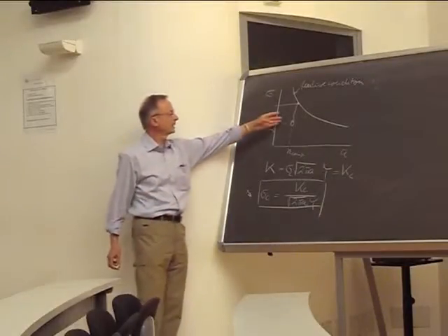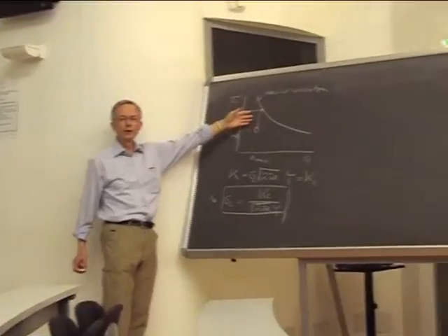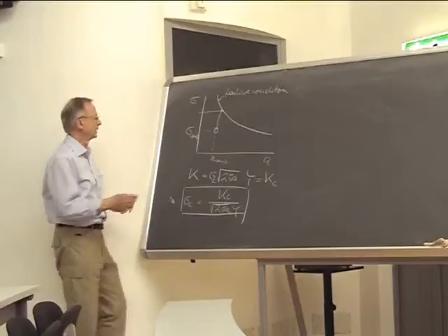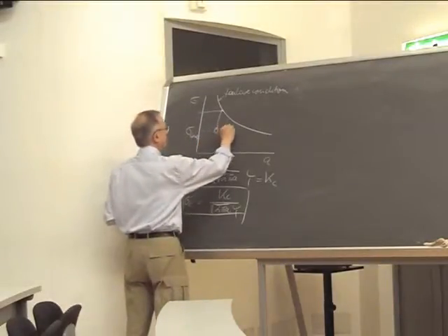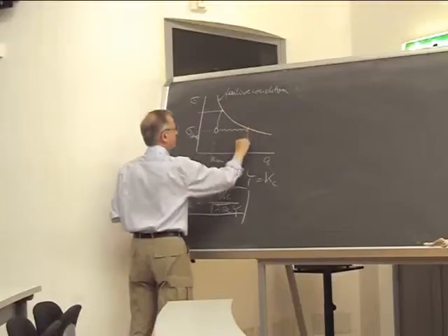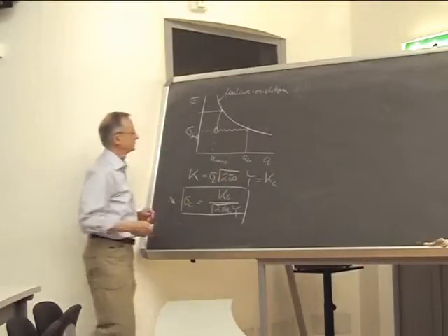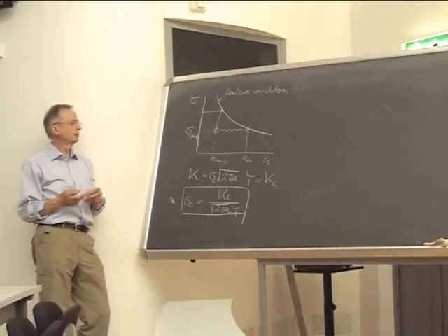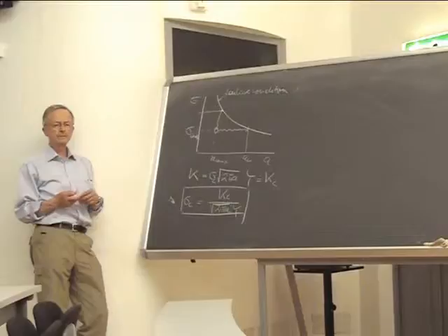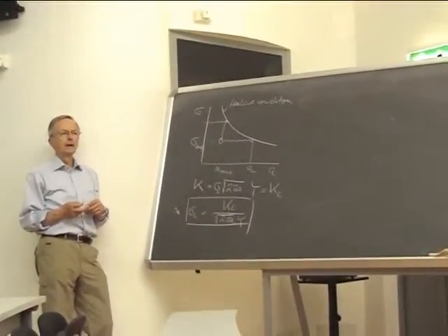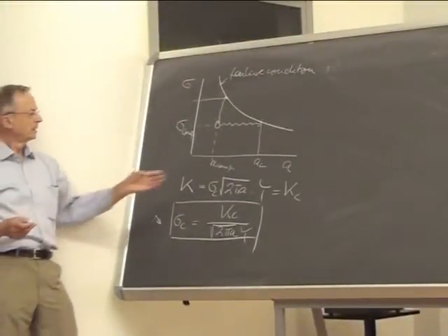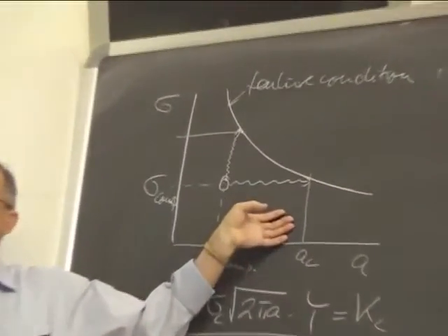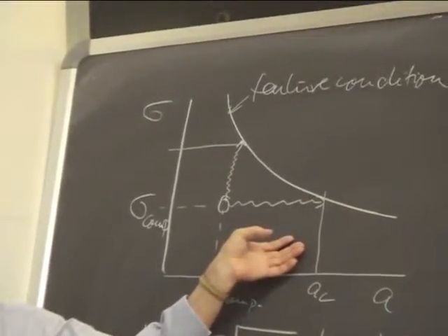Okay, so this is the safety margin in terms of applied load, or internal stresses, or whatever it is. And there's also a safety margin in crack size, a critical. So the crack can extend from the service point to a critical. And hopefully the time from here to there is sufficiently long, for the reasons that I explained before the break.